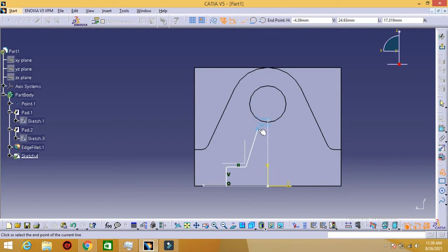My mouse becomes white, which means if I click it here, it will not be either horizontal or vertical. Only when your mouse shows a horizontal or vertical relationship during drawing, it becomes blue. Blue in horizontal, it becomes blue in vertical also. So now take it vertically, see whether it is blue in color, and then click.